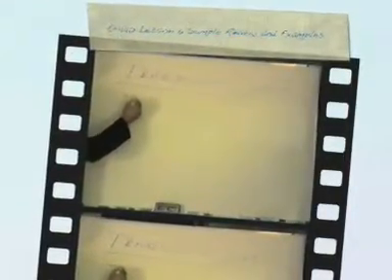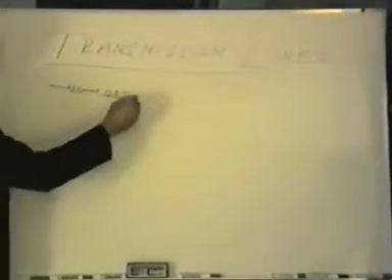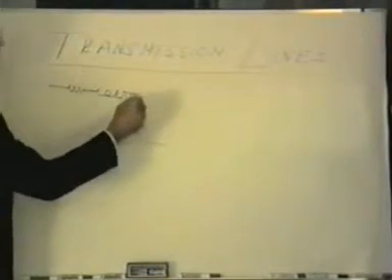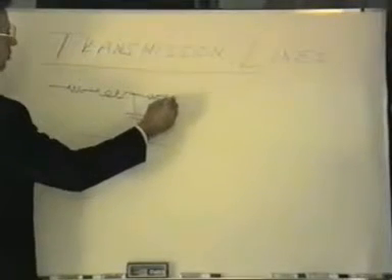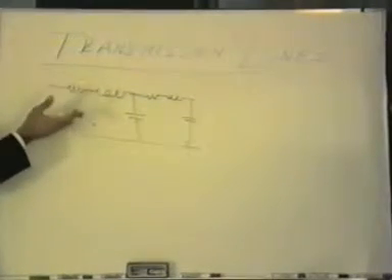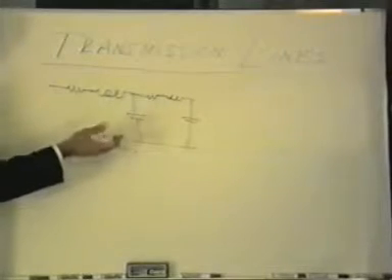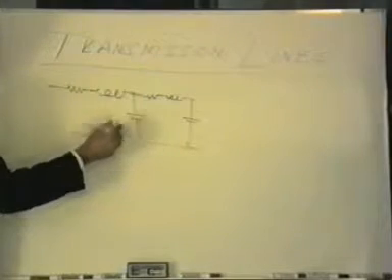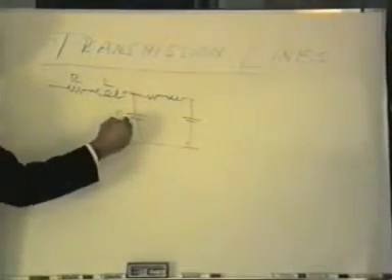A transmission line is characterized by having a certain amount of resistance that's distributed along the line and some inductance, and then we show some shunt capacitance also present, and then this is repeated because the distribution of the parameters goes on. Usually the resistance is given in terms of ohms per mile, inductance in henries per mile, and capacitance in farads per mile. And so the typical line would look like RLC, then it tends to repeat every so often.